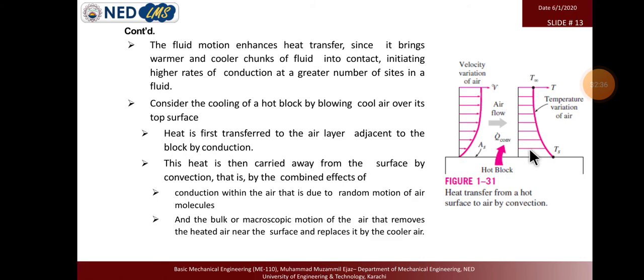We used to calculate this type of complex numerical in mechanical engineering, but in your case, we mostly take the hot object at some distance, and we normally take T infinity as the average or uniform temperature of the room, and take h as the common convection heat transfer coefficient, not the local one.